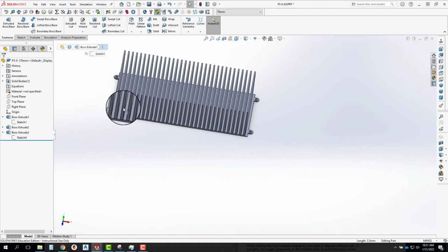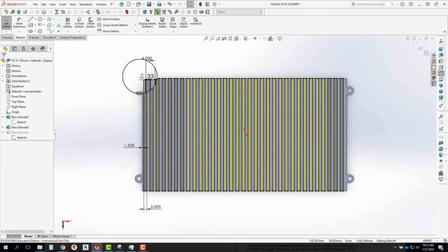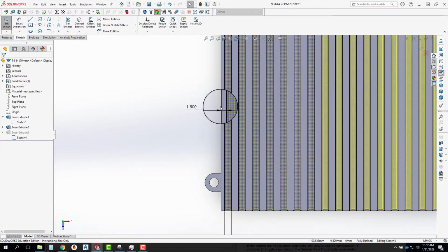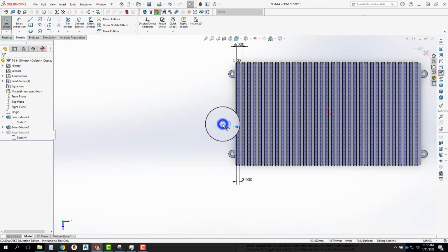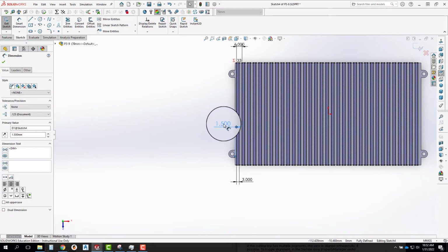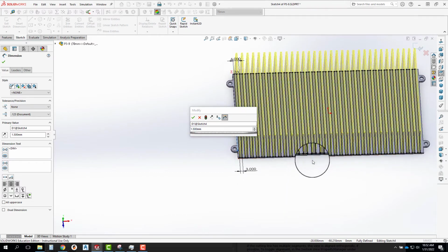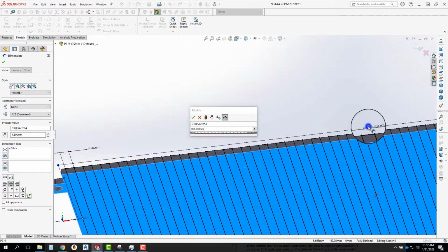So I need to edit the spacing on that first fin so that it always updates as well. Let's go take a look at that same sketch again. Right now that spacing dimension is set. Here it is, it's 1.5 millimeters from the edge. So let's think about how I can redo that one. I want it to be equal to my overall, the full width of the plate. So let's get that dimension again. There's the 200.